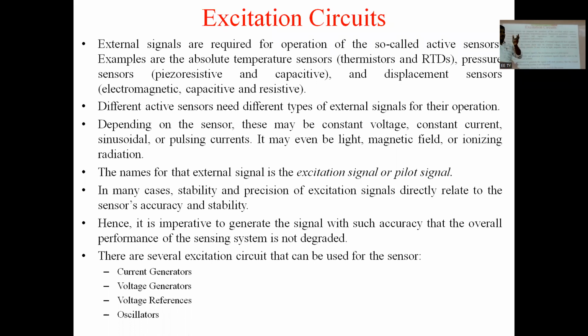So in a DC motor there are three types of motor: separately excited, self-excited, and another one, permanent magnet. Separately excited means we give excitation using a separate DC source. Self-excited means the electricity generated by the machine itself is given for excitation of the coil. And permanent magnet has its excitation, or flux generation, naturally.